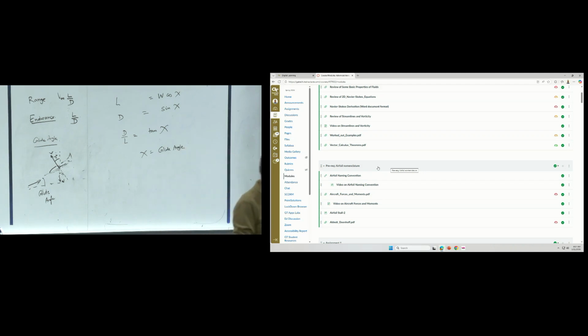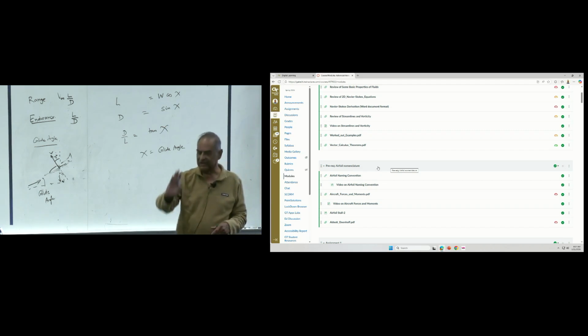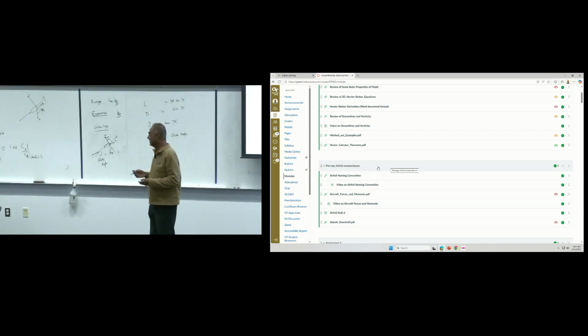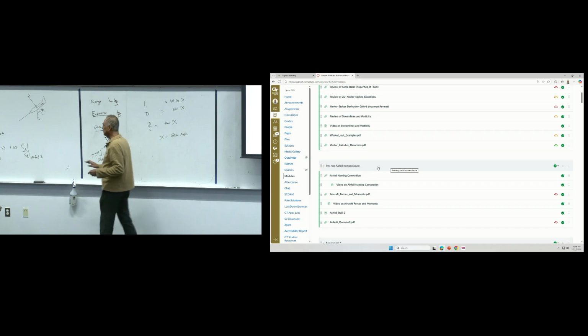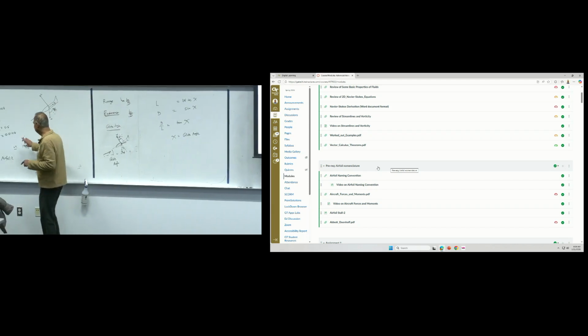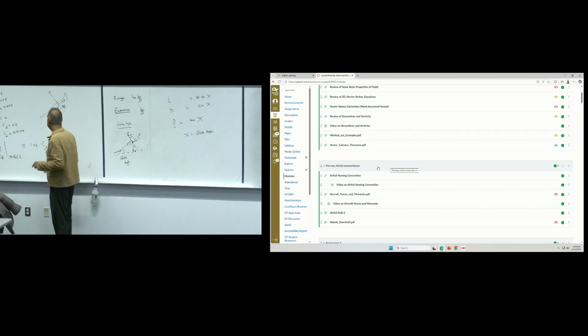So, for example, fighter aircraft get off the ship deck, they need to go very, very far, very, very fast up. Of course, they try to achieve it with a lot of thrust. But if you can aerodynamically make it more efficient, with a very high L over D, your climb angle can be very, very steep. So all of these things mean L over D is very important. Even a 2% change in L over D is very important. That's why we never round it off to just 3 significant digits. We write it to the 4th significant digit.